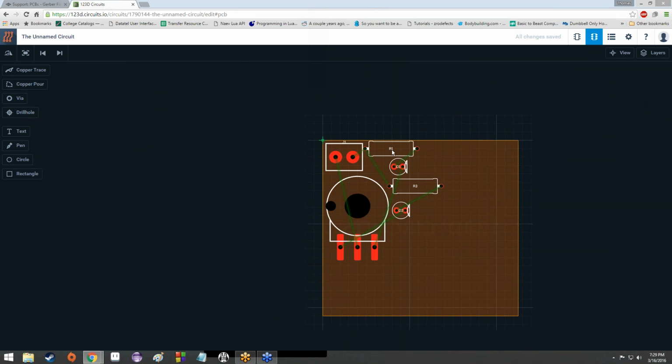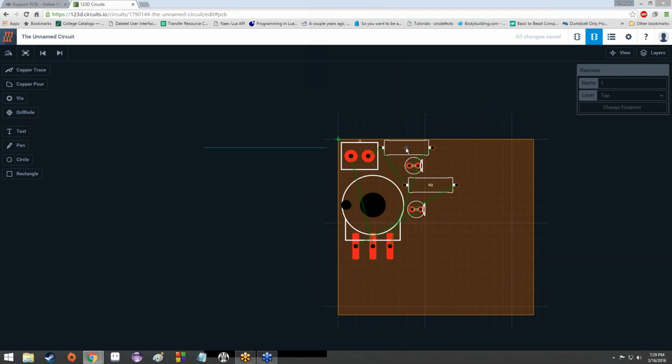Some of you may be wondering why I am fretting about the orientation of everything. And I'll be happy to tell you. It's because printed circuit boards cost money based on how big they are. So, obviously, you have to use more material. And it's not just that. You have to use more etching solution. You have to use more copper. You have to use more of the board material. It's more expensive all around in order to manufacture a larger PCB, more so than you might imagine.